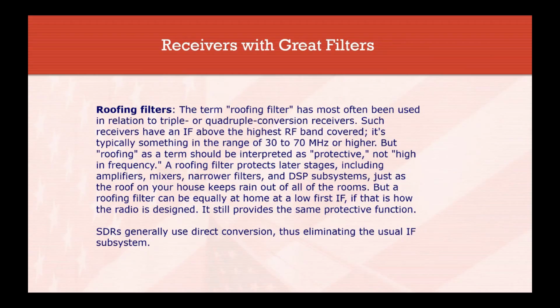Roofing as a term should not be interpreted as highest in frequency. It should be interpreted as protective. The filter protects the later stages from being swamped. That's basically what it's there for. It's like putting a shelter or a roof over their heads to keep the strong signals from wiping them out.